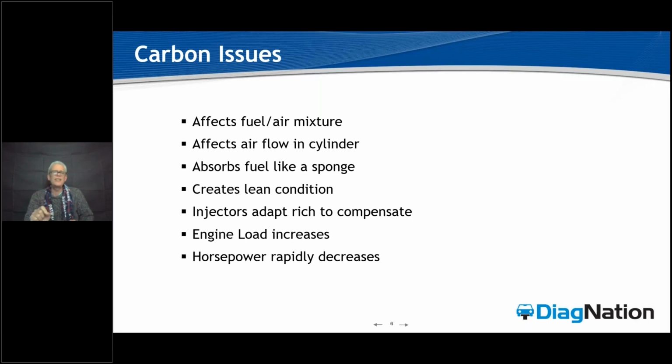Because with all of these GDI cars, it's not like the old days in the 70s where they plunked a piston in a hole and put a high tension ring in it and had it go bang, bang, spark, spark. You guys know, and I know, that it's way more complex from a mechanical movement and engineering standpoint, with the valve phasers and the cam phasers that we have. Everything put into the equation here means we've got an upset in the way that car is running, okay?